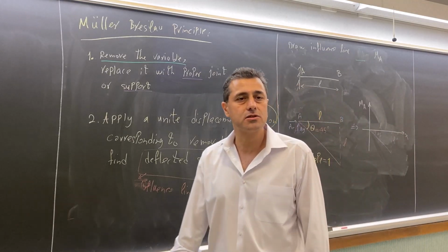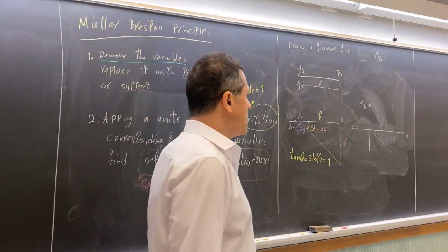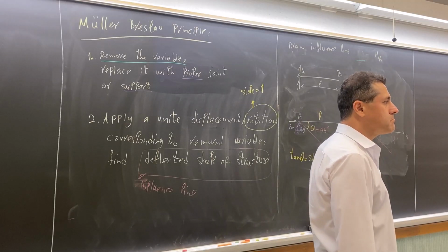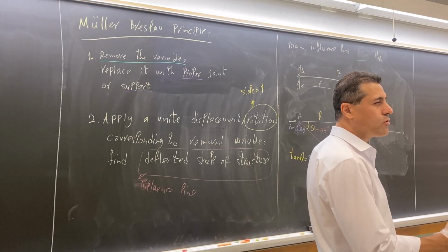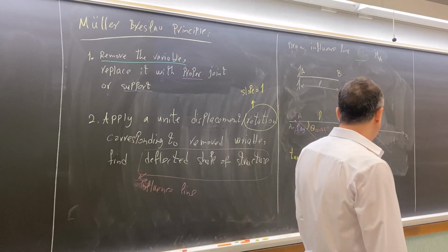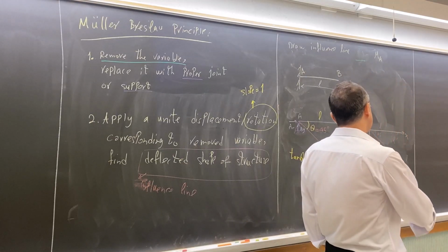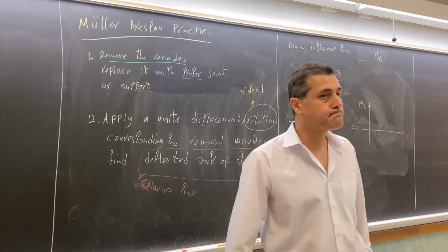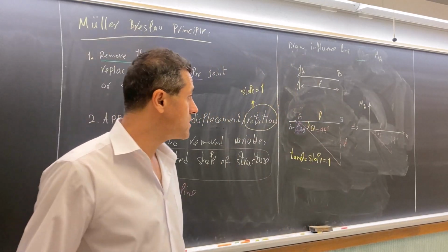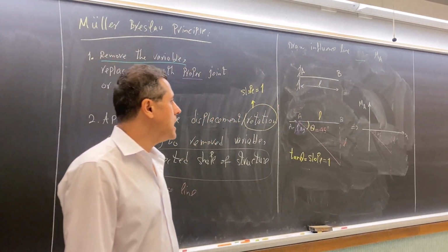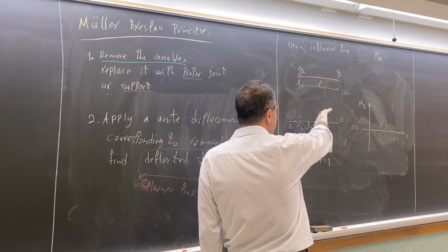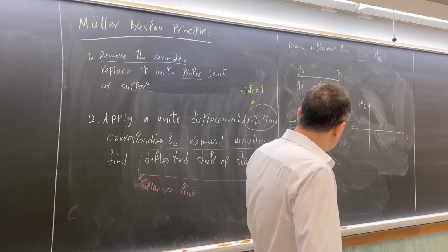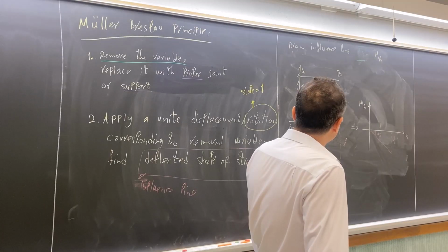The textbook doesn't discuss the angle. When you look at the textbook, you don't see this angle 45, because the textbook doesn't want to go through more details. It's not required. So the slope is unit. It means tangent of theta is 1. It means this is 45. It means this is L, this is L. That's it. Influence line for MA. And the reason we turn it in this direction is because we use clockwise as the positive sign.